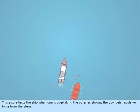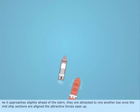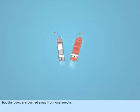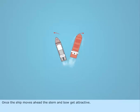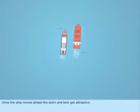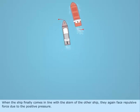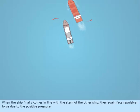The bow gets repulsive force from the stern. As it approaches slightly ahead of the stern, they are attracted to one another, but once the midship sections are aligned, the attractive forces ease up. But the bows are pushed away from one another. Once the ship moves ahead, the stern and bow get attractive. When the ship finally comes in line with the stern of the other ship, they again face repulsive force due to the positive pressure.